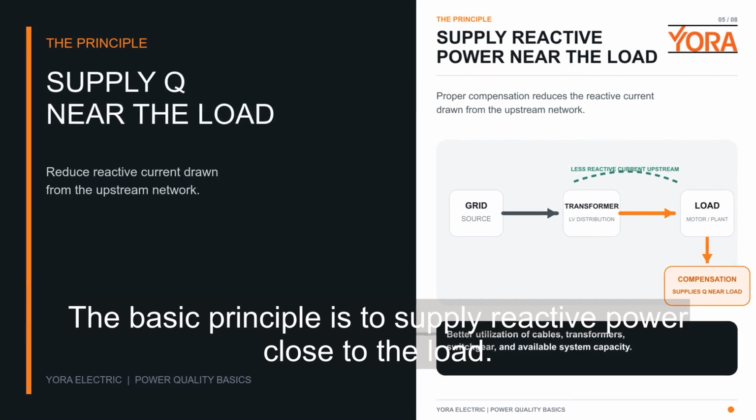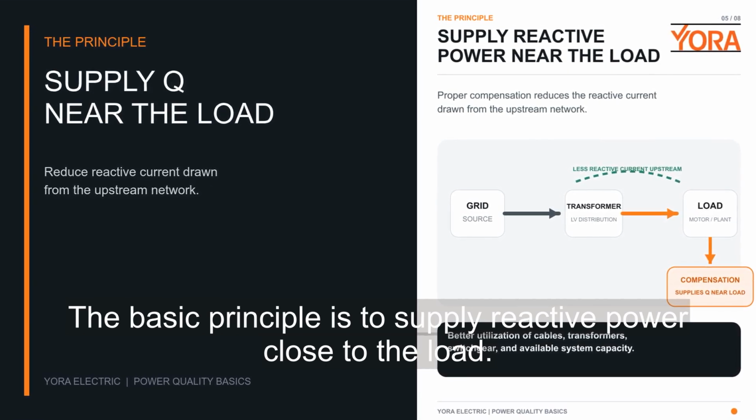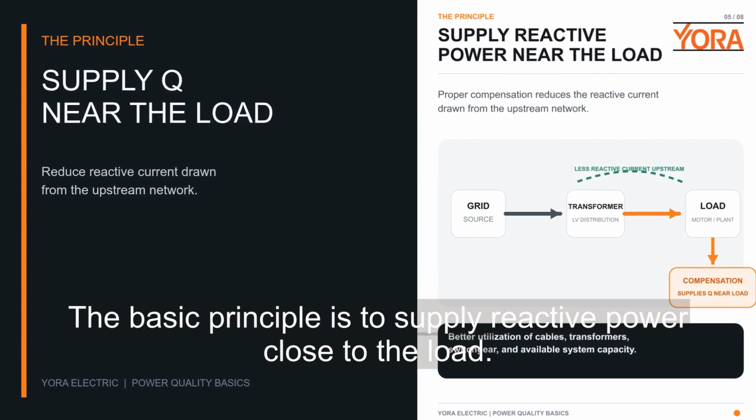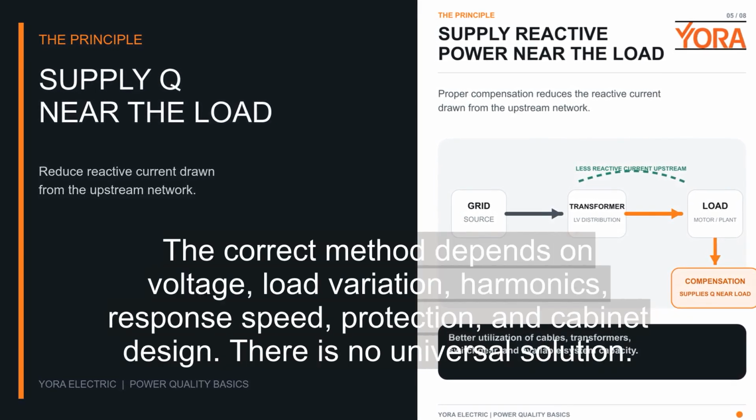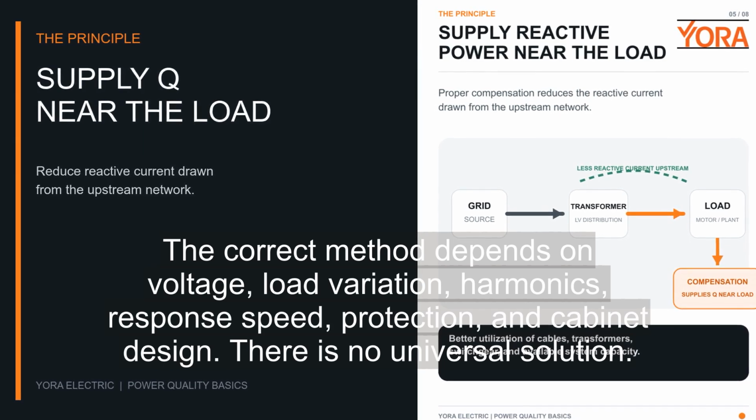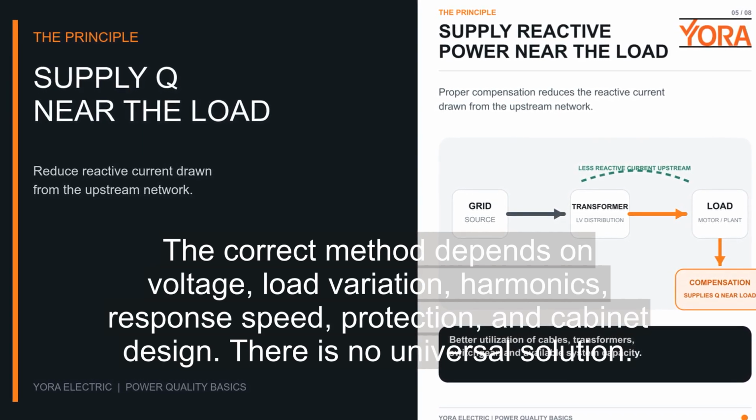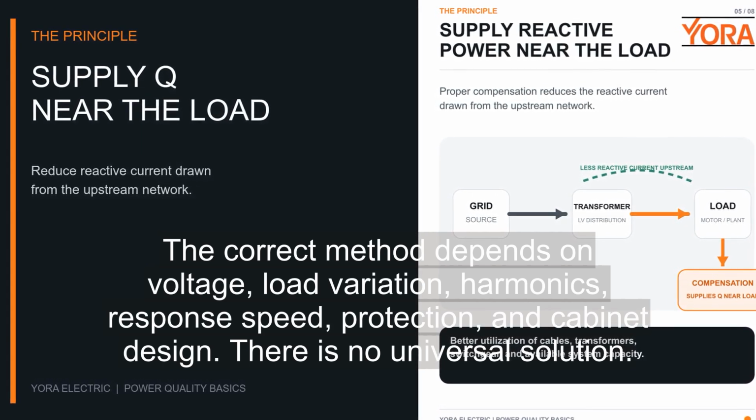The basic principle is to supply reactive power close to the load. The correct method depends on voltage, load variation, harmonic conditions, required response speed, protection, and cabinet design. There is no universal solution.